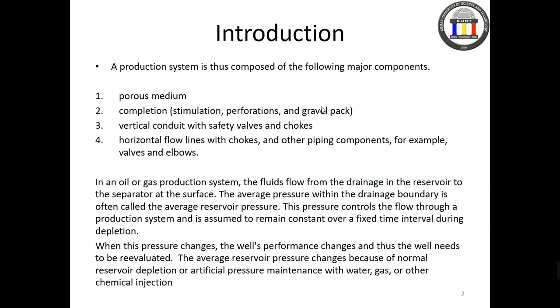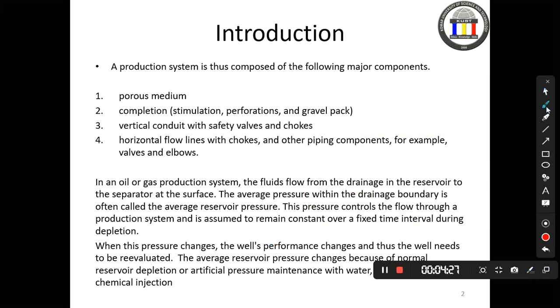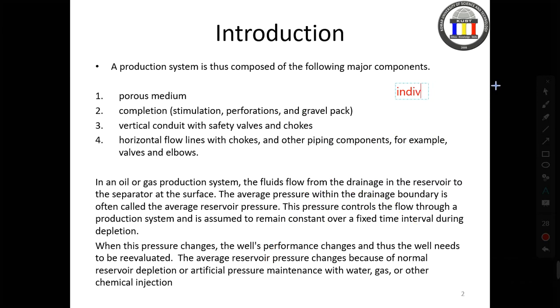Now, based on this nodal analysis, the production performance can be of two types: individual well performance, or field performance. We have to look at both. For the individual performance, we go for Prosper. We do the IPR, we look at the water production, we look at the pressure drops, whatever parameters we have, we evaluate their performance, and then we look at the field performance.